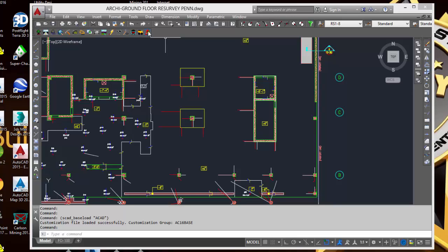And this movie is to show you how once you create the points in Carlson Survey, you then exit out, save, exit out, and go into a brand new drawing and insert, not open, insert this drawing and rename it to US feet as opposed to Archi or Arch.